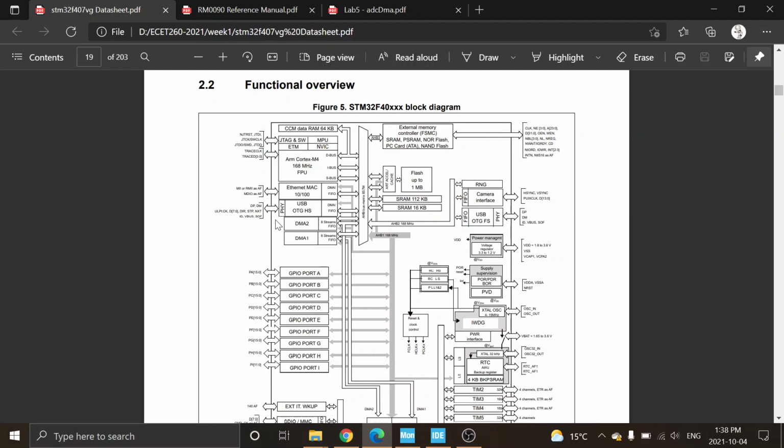It can do that. Now, in amongst the DMA, there's also something known as a bus arbiter, because a DMA controller is a bus master, so it can take over the bus. It can go and control where things are. But your ARM CPU is also what's known as a bus master, so it again can take over the bus. So you have all of these devices that are able to take control of a bus and move data across the bus. And so you have something known as a bus arbiter that says, okay, DMA1, DMA2, and the CPU all want the bus. Who gets it?